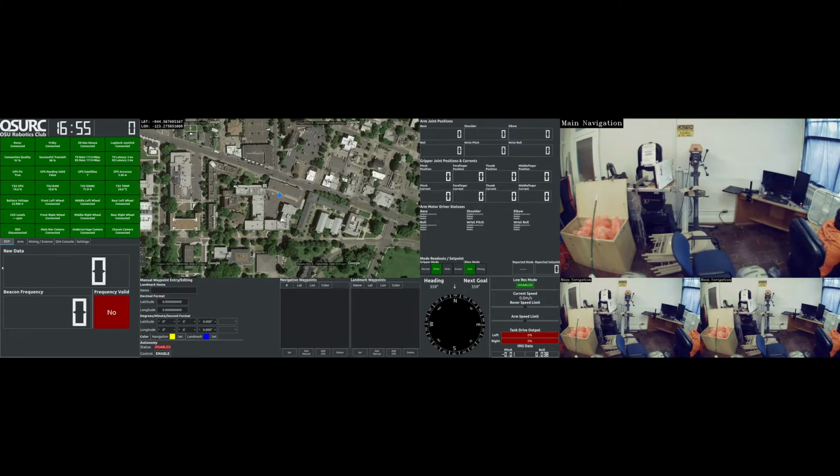Then down here, we're going to take a look at the radio direction finding tab. This entire area is a tabbed group for all the miscellaneous functions of the rover. The raw data readout here is essentially the raw analog output from the Teensy on the radio, averaged over, I think, a window of 100. It's a rolling average. And at the bottom, we get a readout for the FFT of that data to give us the most common frequency.